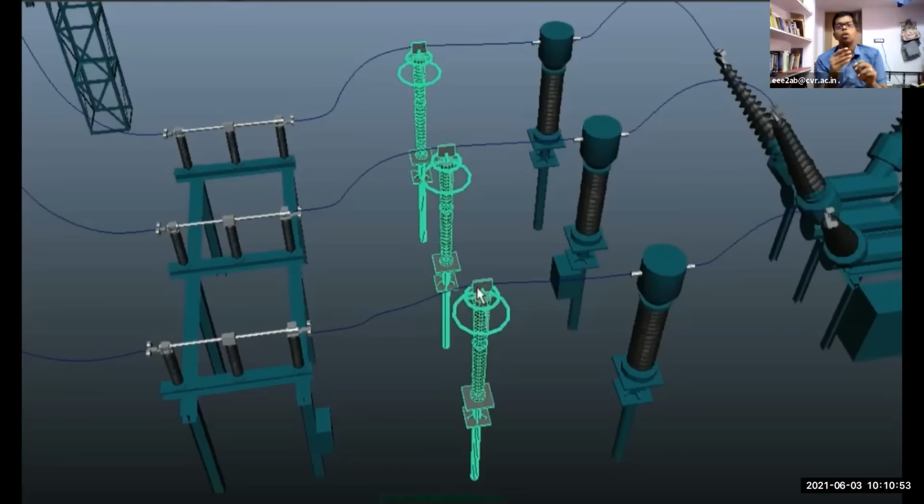Simply like that, that much voltage coming to the particular line will affect the whole system, because CTs are there, PTs are there, and your circuit breakers are there, everything gets spoiled. So even though the circuit breaker will automatically trip, sometimes it will affect your circuit breaker also. So the surge arrestor is there to suppress that particular surge voltage.